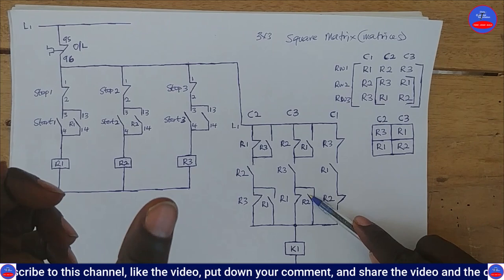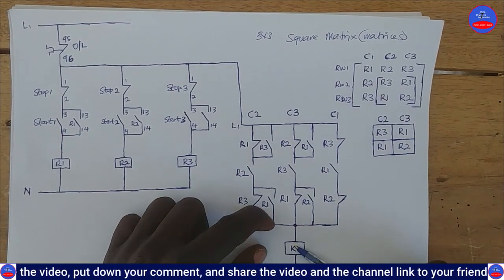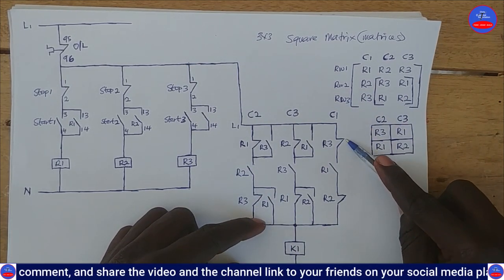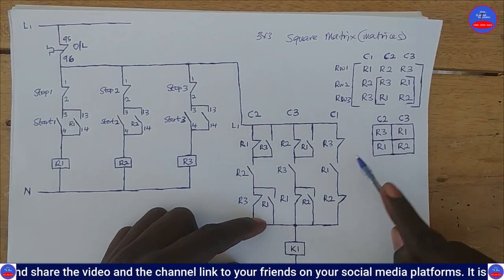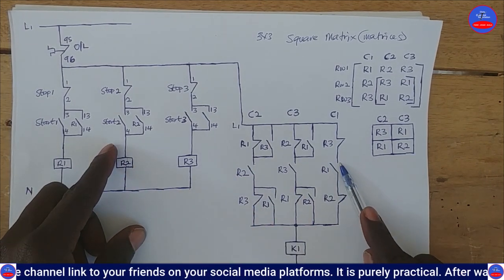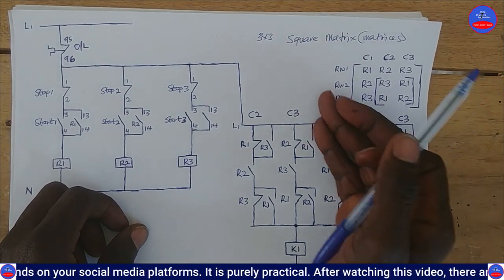Because all the 3 relays are all on, it is still energized. But the R3 is closed, this side is open. The R1 is energized, so this side is closed. The R2 is energized, so this side is open. So this side is not part of the path.